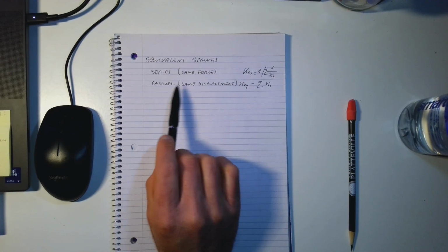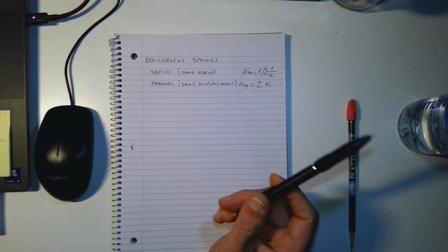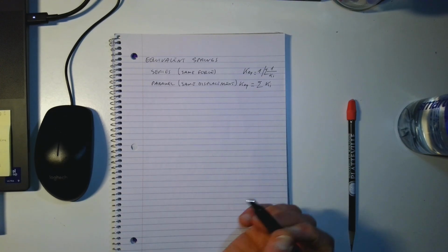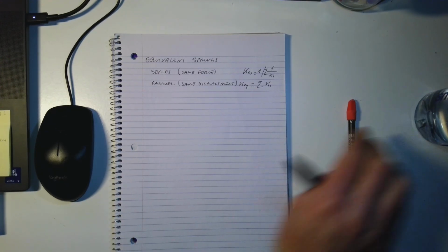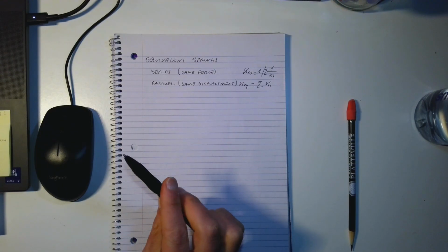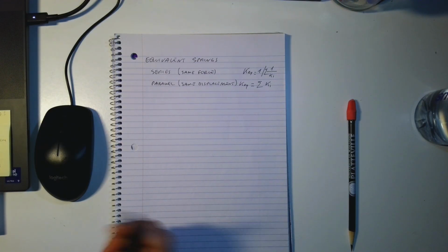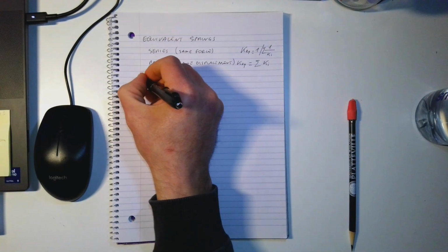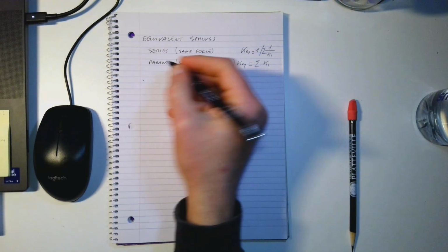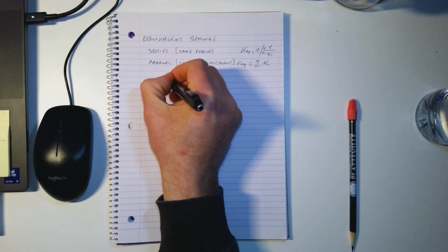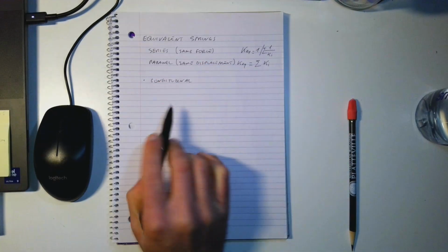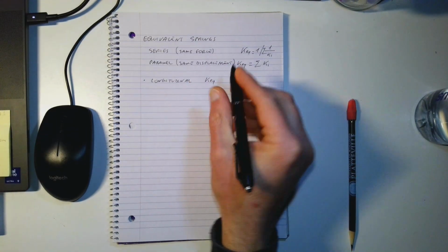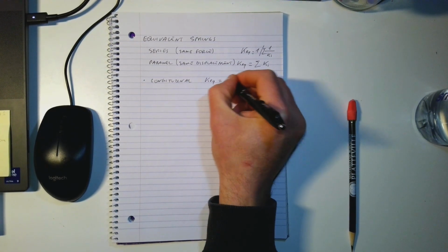We also looked at equivalent springs from a different point of view, because we said that materials that are elastic, or in general linear elastic, also behave like springs, depending on what type of motion we have, for example, a beam. In this case we also listed 4 examples. The first example is when we have longitudinal motion. When we have longitudinal motion, we can come up with an equivalent stiffness, which is given by EA over L.